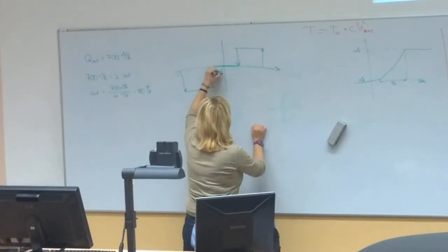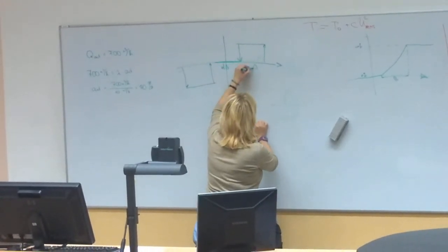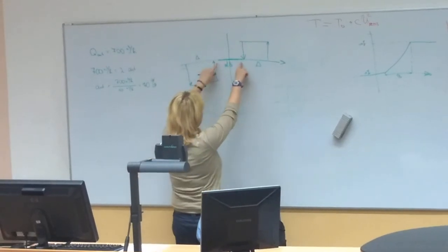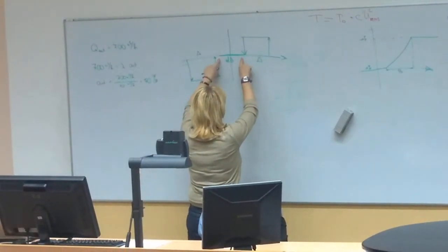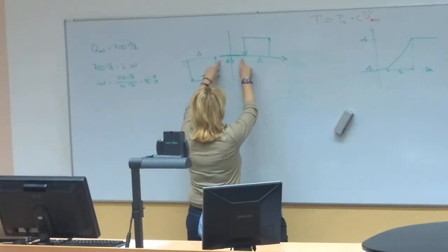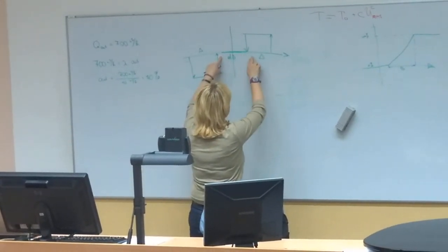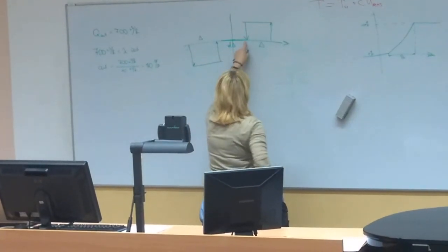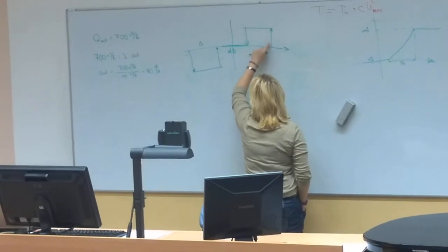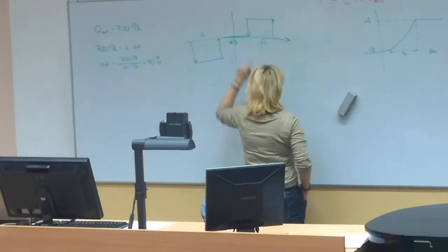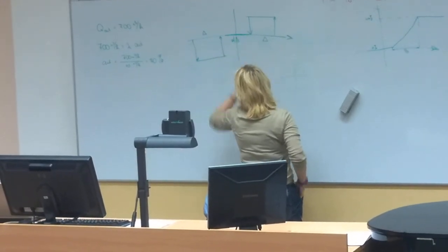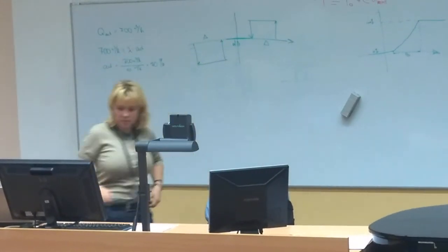And this is deadband, and this is hysteresis. So basically, if the error is small and it remains within that period of deadband, then nothing happens, our motor stays. And if our error goes further, then our motor tries to move and tries to bring our error back into that range.